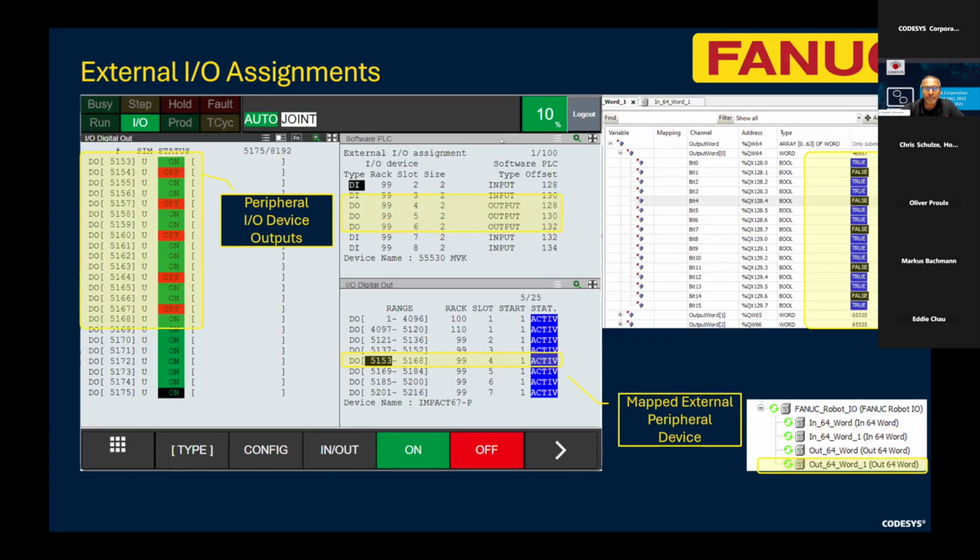Likewise, digital outputs can be turned on in CODESYS to trigger the actual device output modules. Here we see 3 consecutive Profinet output modules are being controlled by the CODESYS program, which turns on the respective outputs. It should be noted here that when this data is mapped to the CODESYS, these outputs cannot be turned on by the robot controller. However, just like before, we can still monitor them inside the teach-pendant programs to satisfy conditions that would be used for the next steps.